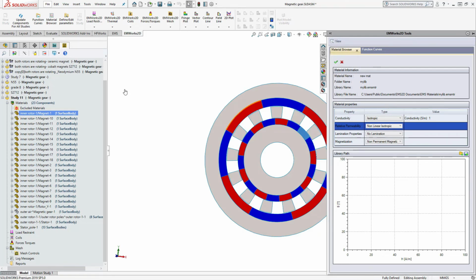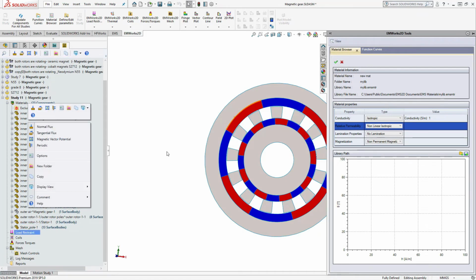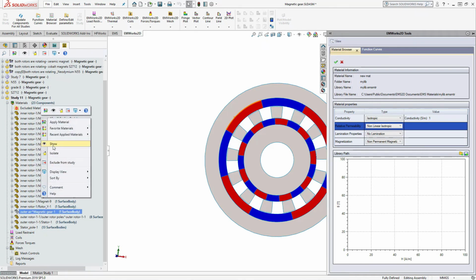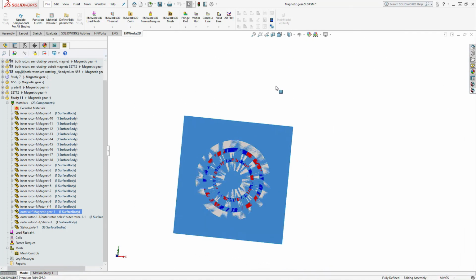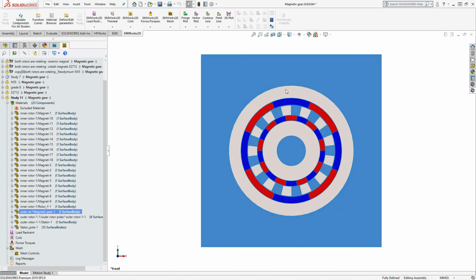Okay, so you define your materials, you define the boundary conditions. It's simple. Only one boundary condition is needed. You apply a magnetic vector potential to the outer edges of your system or your region. For example, here we should apply a vector potential to these outer edges.